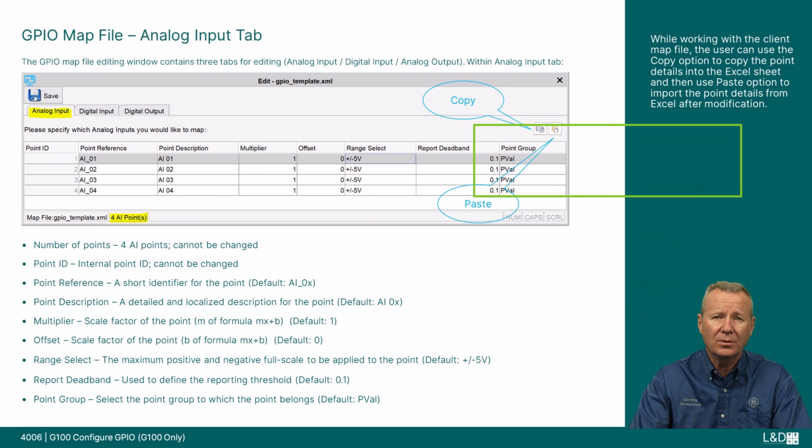The default is on. Off state: text description of the 0 state which is displayed in the local remote HMI when the respective digital input is in the off state. The default is off. Note that the constraints on the naming convention for text description for the on state and off state are the same as existing applications in DSAS's configuration tool.